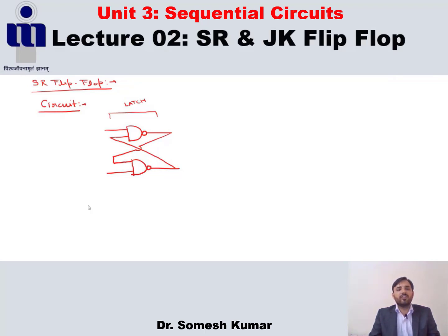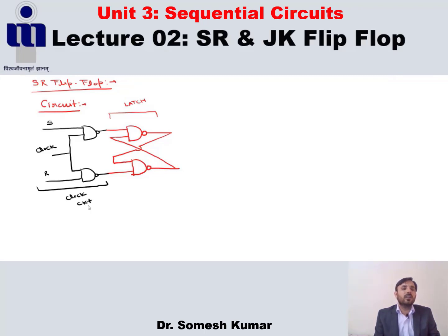The basic difference between flip-flop and latch is that a flip-flop may be edge triggered or level triggered, while the latch is always level triggered. So if we connect two more NAND gates here, and these two NAND gates are controlled with the help of one input called the clock, and these two inputs are S and R, this is basically our clock circuitry. And this complete circuit is called our SR flip-flop.